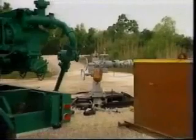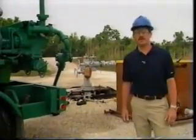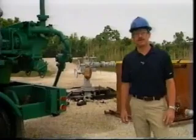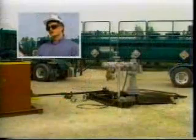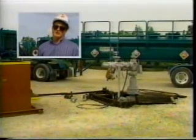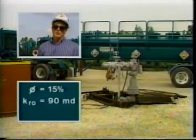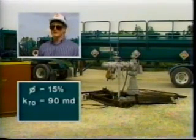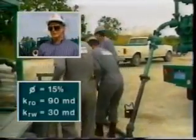Now that we've looked at 2 treatments of carbonate reservoirs, let's consider a matrix acid treatment of this sandstone reservoir. We'll review the design carefully and then observe its execution firsthand, including procedures, equipment, and quality control. This well was completed in a 30-foot sandstone section. Porosity is approximately 15%, relative permeability to oil is approximately 90 millidarcies, and relative permeability to water is 30 millidarcies.